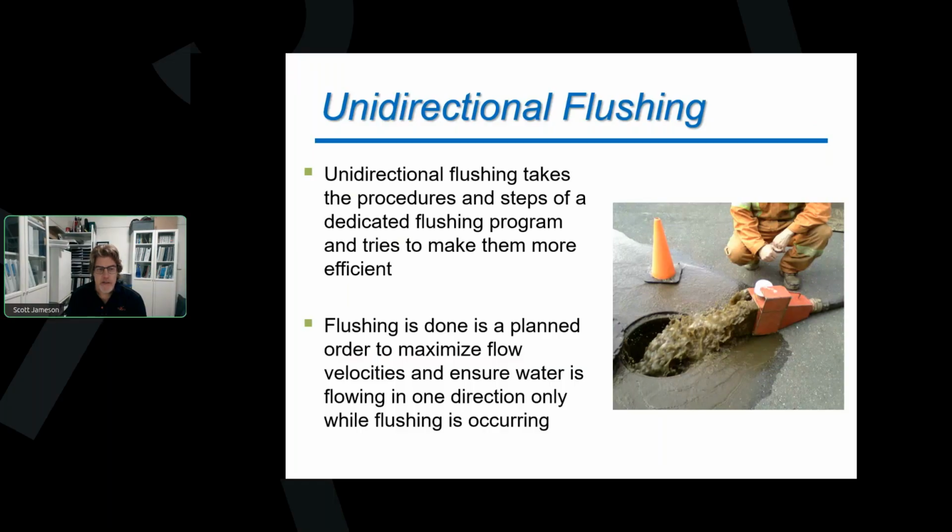And the overall idea is that we're going to do the flushing in a very planned way, make sure that the water is only going in one direction only. And by doing that, we're able to maximize that flow velocity, right? And we get the best scouring that we can possibly get with our flushing program.